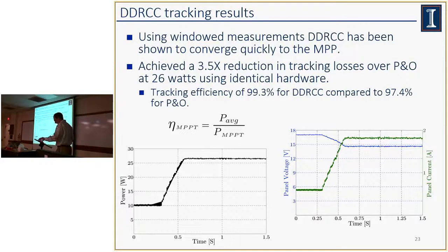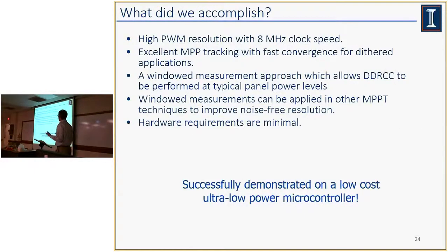So with that, basically what did we accomplish? We accomplished high PWM resolution using an 8 megahertz microcontroller, and we were able to accomplish great maximum power point tracking with this dithered approach.